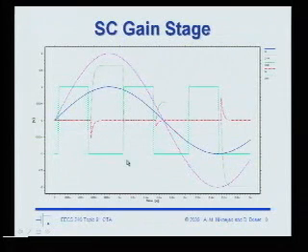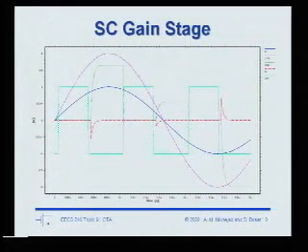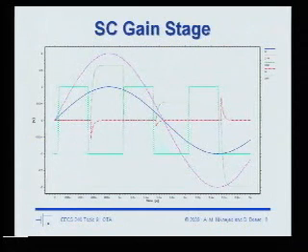So what value, what time period should I look at? The end of phase 1, the falling edge of phase 1. Precisely. It's the falling edge of phase 1, because up until this point, the CS is actually being charged to V input. And if it can charge fast enough, it's essentially following V input. As soon as that edge falls, I've captured this point.